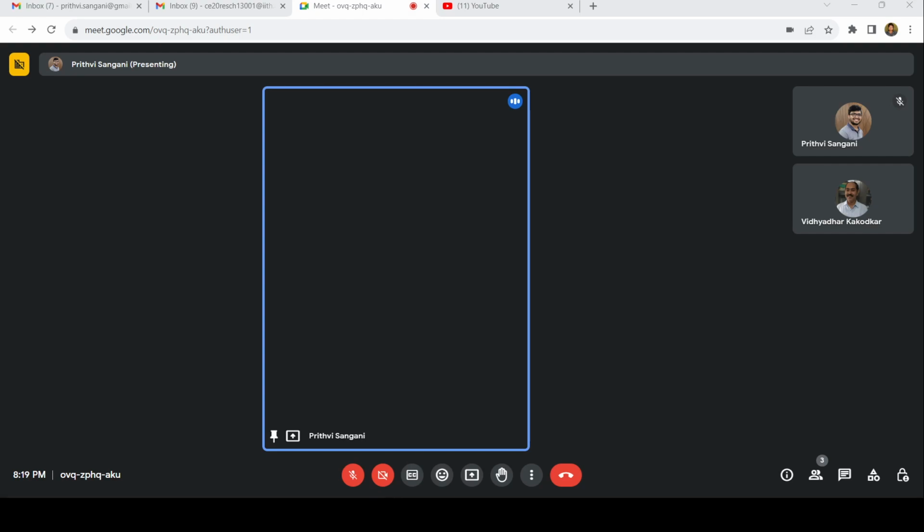So my delta 2 will be, I'll apply a unit load downwards direction 1 kilonewton, and because of that I will have internal forces vi. Okay. So my delta 1 is going to be summation fi ui li by ae. My delta 2 is going to be summation fi vi li by ae.